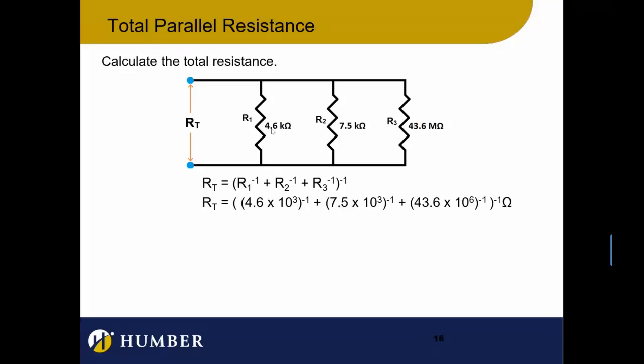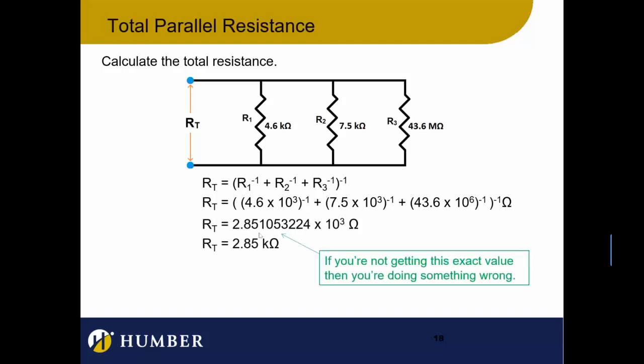Because I know that 4.6 kiloohms, you can type in 4600. You can do that if you want. But I need you to practice doing this. Use engineering notation: 4.6, and then EE 10 to the 3, or EE3. Practice that, and you'll have to do it for this one too, unless you want to type in that many zeros, which will screw it up. And then the answer is this. Great. Your calculator is going to show you this.